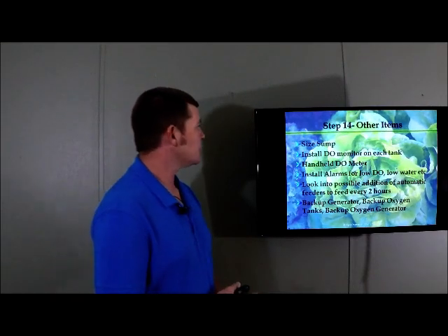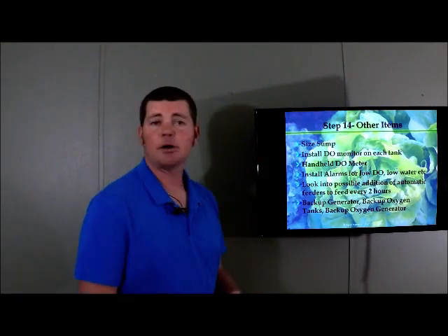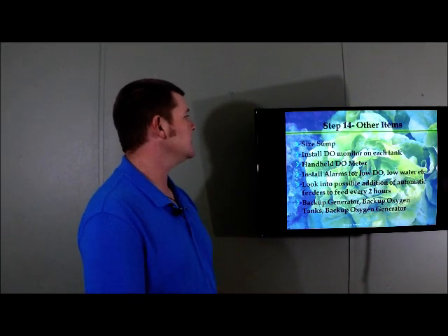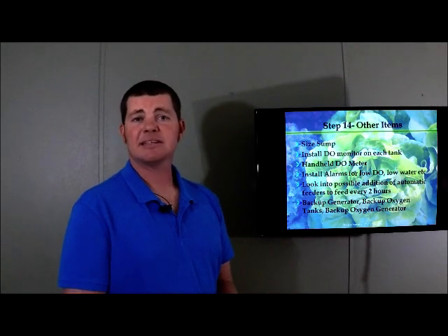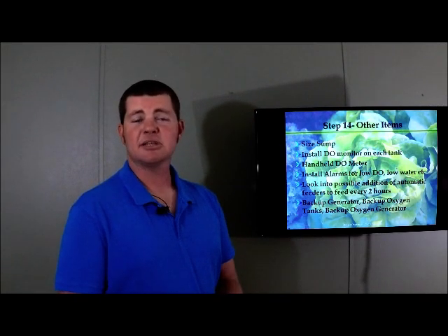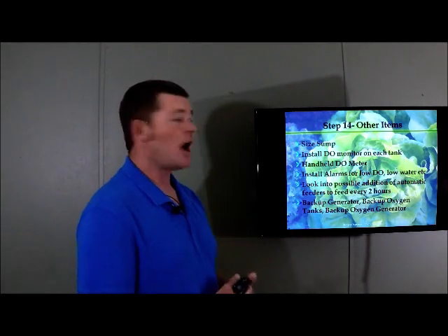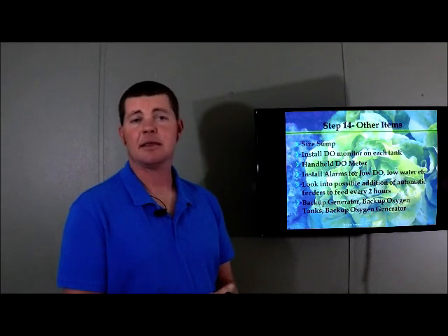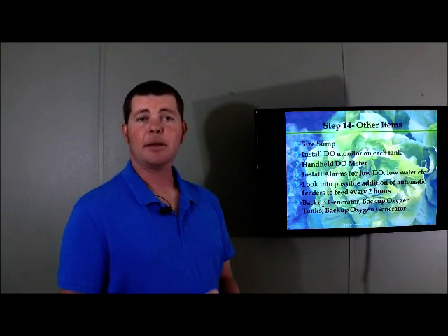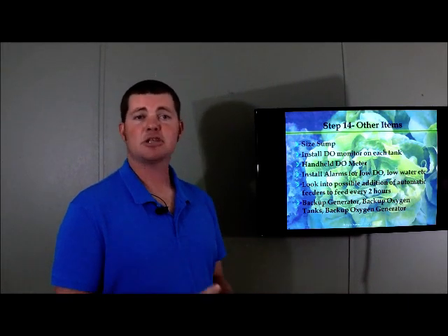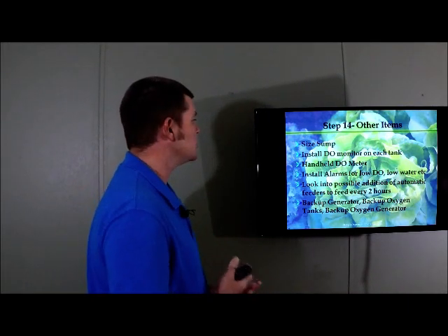Some other items to wrap it up. We need to size the sump. We already know how to do that. We need to install a dissolved oxygen monitor on each tank. This is a must. Okay, this is high density production using pure oxygen. You want an alarm system to let you know if oxygen levels drop, and you also want bottled oxygen that will be delivered to that tank in case oxygen levels drop and in case of an emergency. You do not have long to react when fish are at these kind of dense populations.